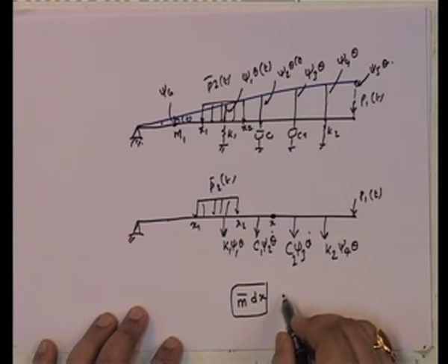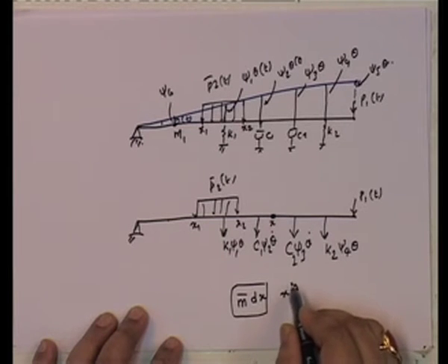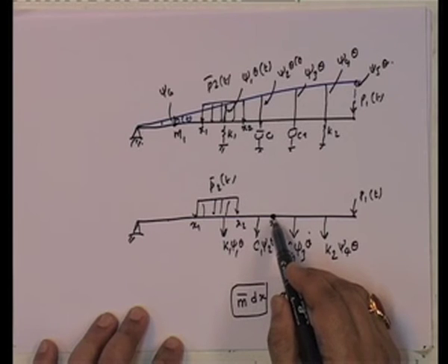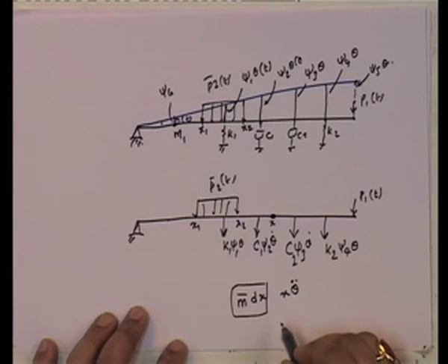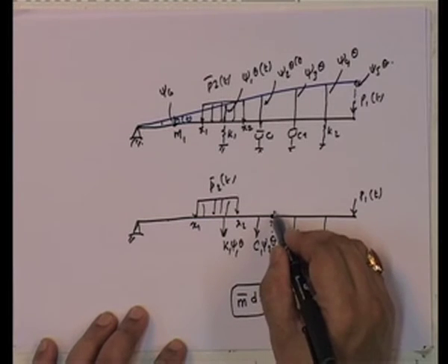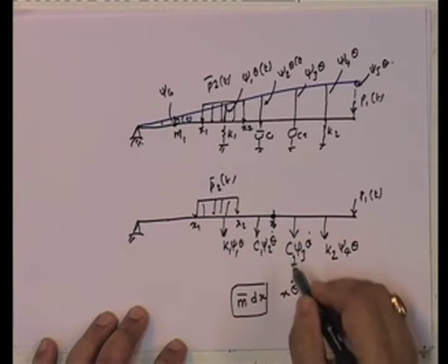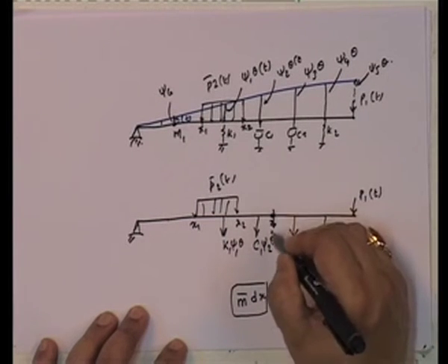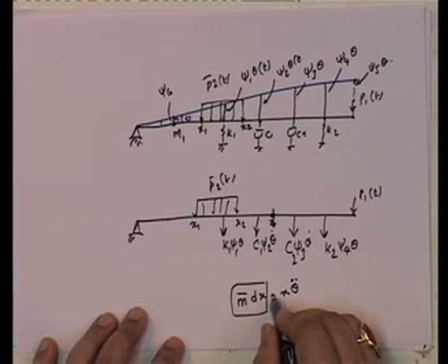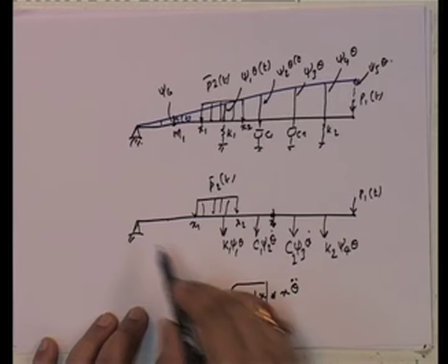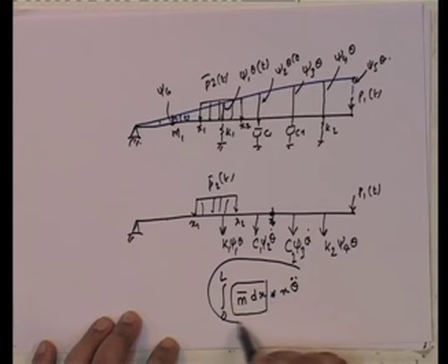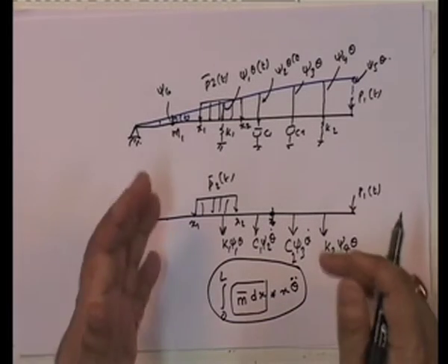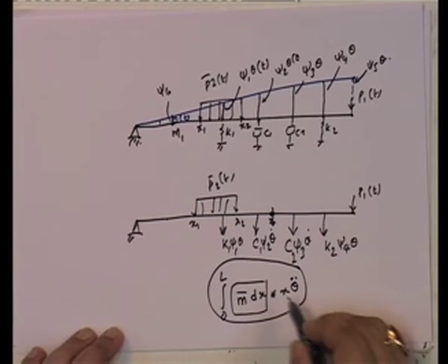It is going to be subjected to an acceleration that is given by x theta double dot. Remember, x is a position. So, x does not vary with time. However, theta t varies with time. So, this is going to be subjected to this acceleration. So, therefore, what we have is that this particular one is going to give rise to an inertial force that opposes the motion. Okay, and that inertial force is equal to this, and so therefore, this one is to be integrated from 0 to L to get the entire mass, the inertial force. Okay.